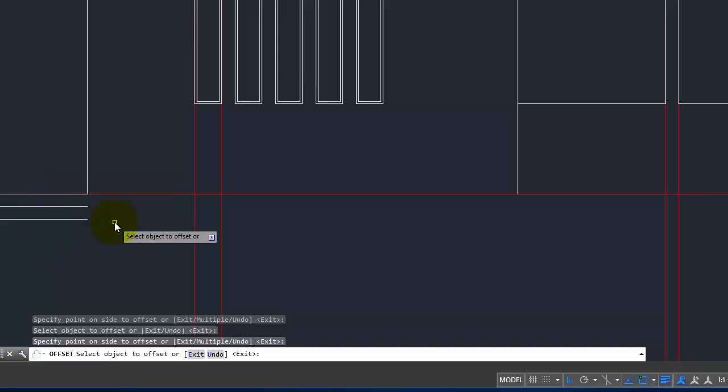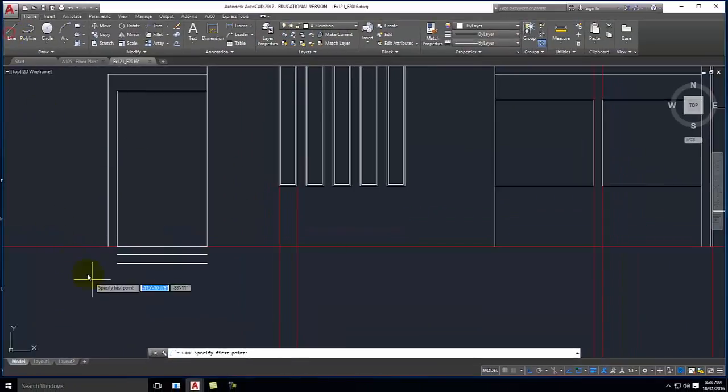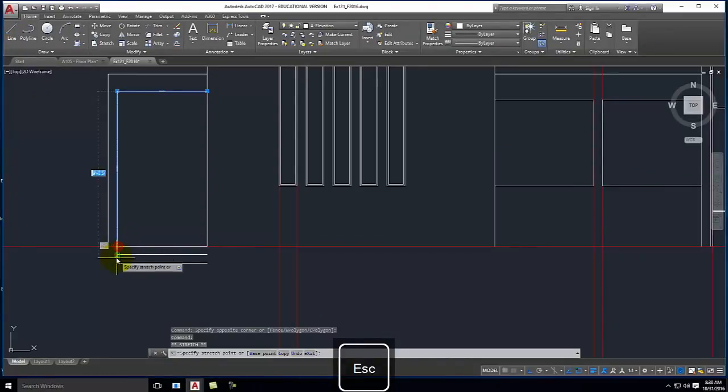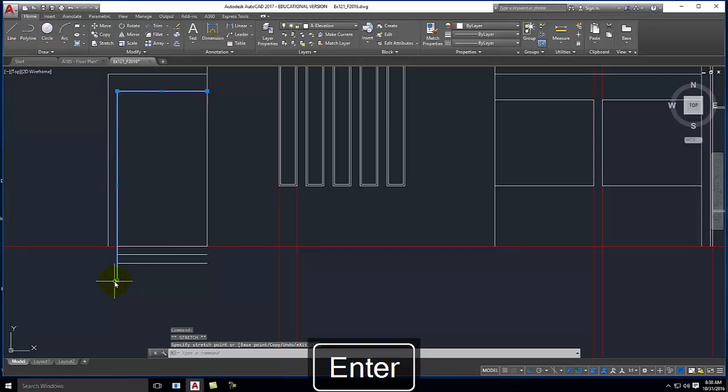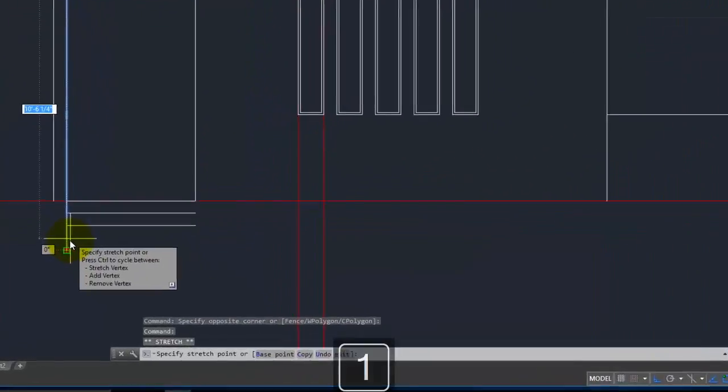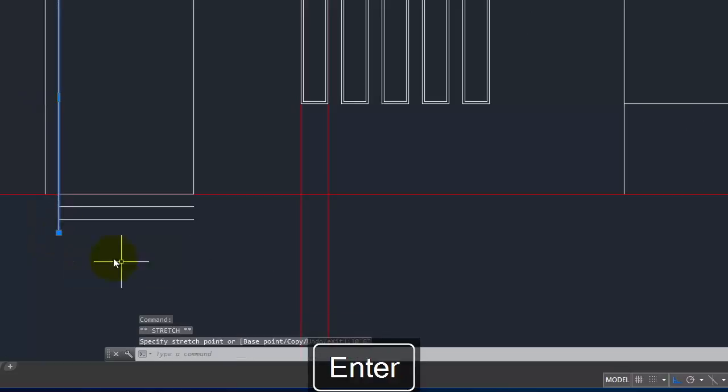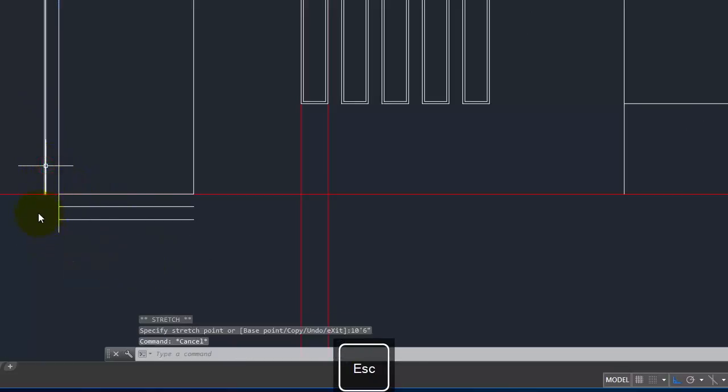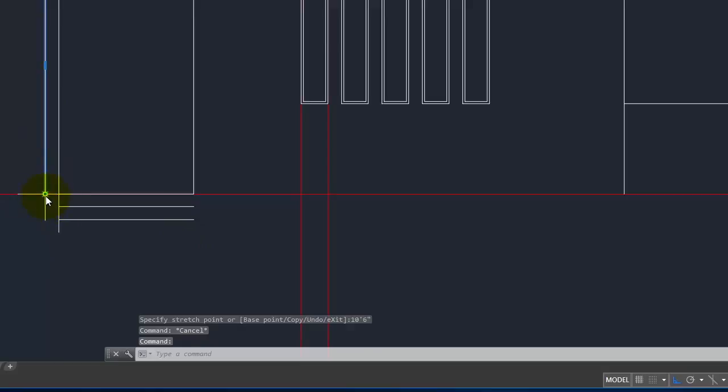So that's my lowest stair. There's probably 6 inches below that point. So I'm going to need to take this wall, pull it to there, and then I'll need to add 6 more inches. So if it's currently, well, this would currently be 10 feet. I could say this is now 11 feet. Oops, no, that was wrong. Should have been 10 foot 6. Sorry. Feet, 6 inches, like that. I can pull this line down as well, maybe. There we go. Make it match there.